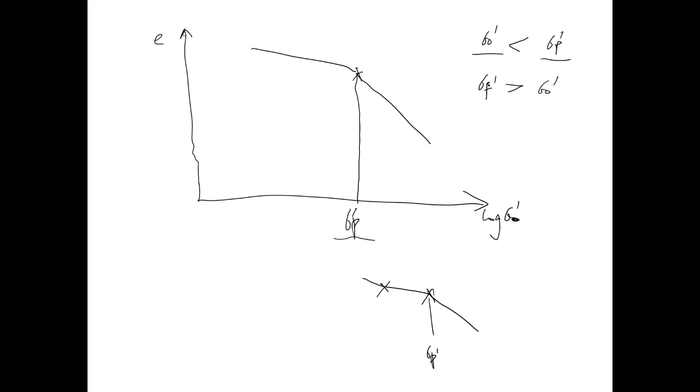If the sigma F prime you work out is also less than this one, then obviously your initial effective stress and final effective stress are all less than the pre-consolidation stress, and then you use the OC formula. Otherwise, if your final effective stress and initial effective stress are greater than sigma P prime, you use NC. And the third scenario, that's the OC plus NC.